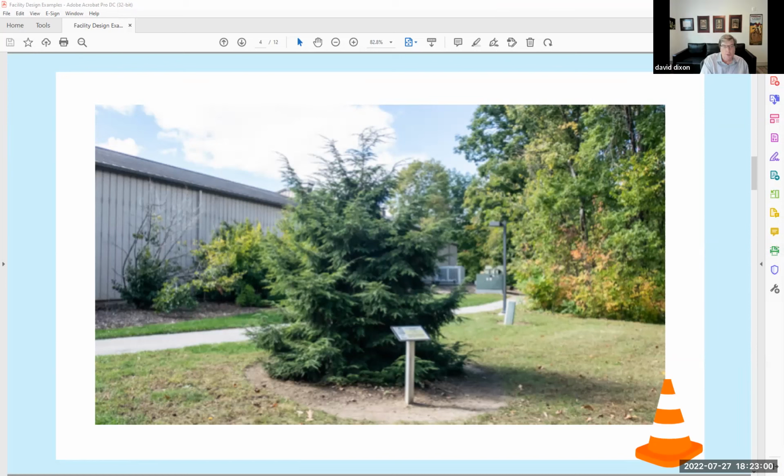And the closeness of the landscaping to the building is a problem. Usually you want to have at least 6 feet to any plantings away from your wall. And there's usually lists of don't plant these near your facility. A lot of fruiting trees and specific issues that are harbingers of specific pests. Mm-hmm. And I'll pick up on what David Dixon just put down.